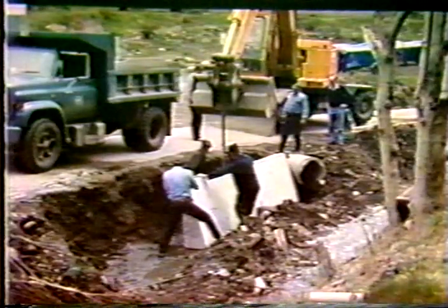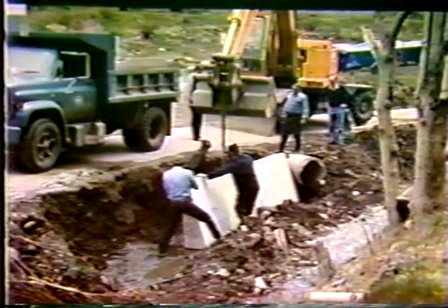What they do is excavate a little part of the slide area out and place the wall in, and here's a little more construction detail. You notice there are 2 hooks on each adjacent wall. When they precast these, they leave some reinforcing steel hanging out at each end. They bend one end over and fit it through the hook, and bend the adjacent reinforcing steel through the hook of the other. So he ties the walls together. I think it's kind of a neat design. And like I say, he can place these very quickly. Here's another close-up of the locking mechanism that he came up with.